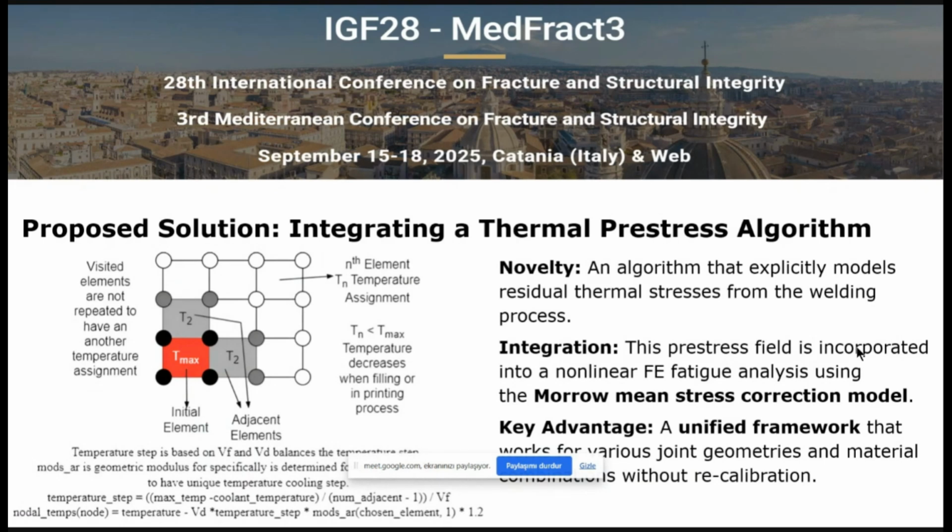This geometrical aspect means we calculate the geometric modulus. Geometric modulus is used in sand casting. It's a parameter used in cooling to understand how a part will cool, maybe a sudden cool or a slower cooling process, which matters for bigger parts in casting.